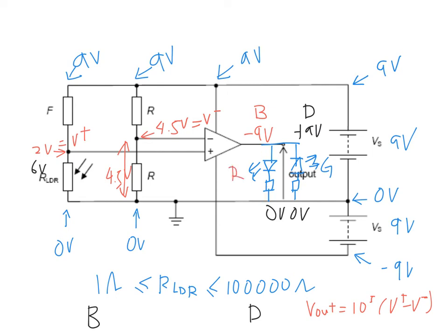Okay? So you can actually replace this with a relay if you want to, instead of turning on and off the LED to show you whether it's dark or bright. Let's say you want it to turn on an external light, that means a porch light. So let's say at night, automatically it turns on when it's dark, and in the morning it automatically turns off. Then you don't use LEDs, you use relays.